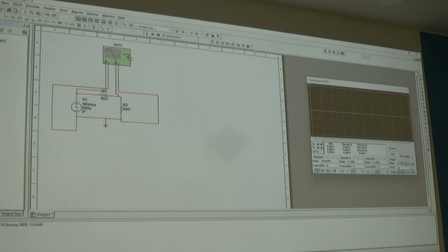So if you do some measurements on it, however you measure it, but peak to peak is probably the way that most people would measure it, you'll see that one of those signals is half what the other signal is. That's what you would expect, right? Because you've done the experiment with the DC, and half the voltage is dropped across one resistor, half the voltage is dropped across the other resistor, and you're looking at the voltage in between. Yeah. So that's great. That rather reinforces the theory that we had before.